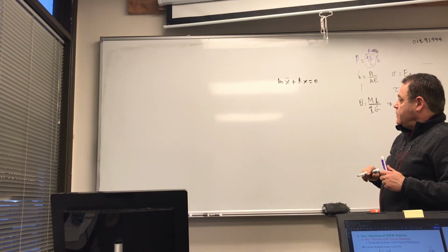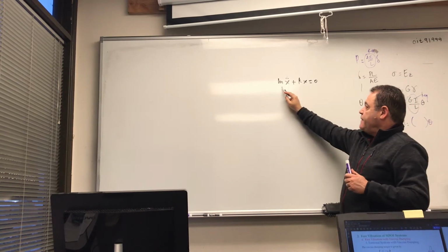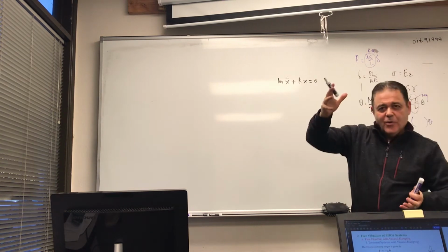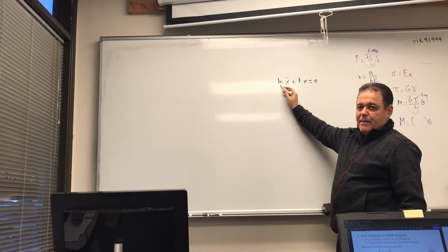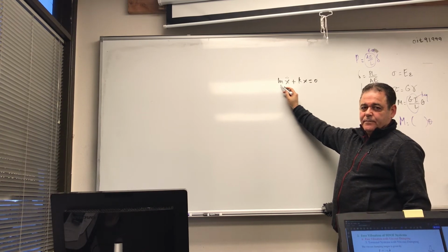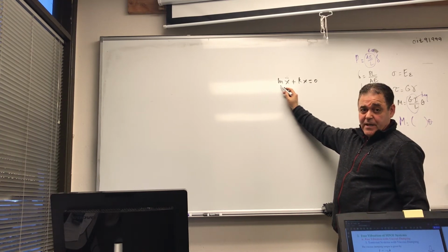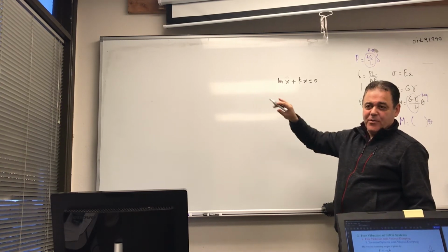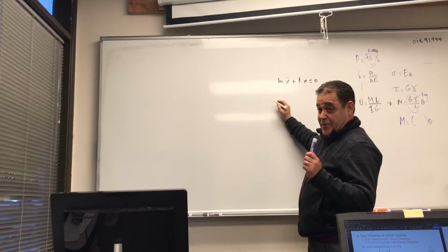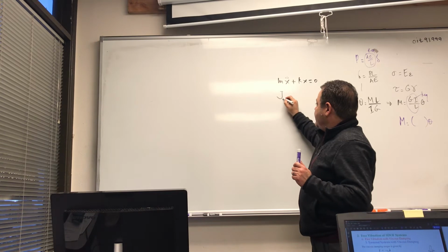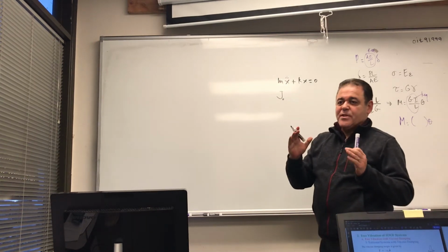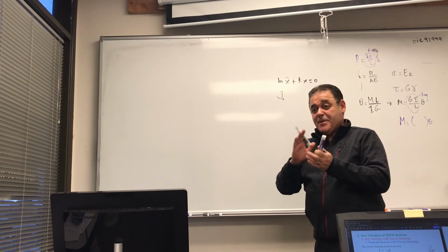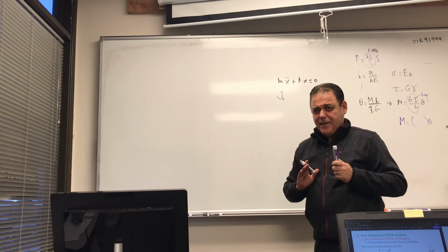If I want to write an equation for something that is rotating, what would replace M? We talk about this in dynamics all the time. What replaces M in a rotation? I. In this book he calls it J, which is the mass moment of inertia. You can call it I, but this book uses I for area moment of inertia and J for mass moment of inertia. In dynamics, we typically don't have those occurring at the same time.